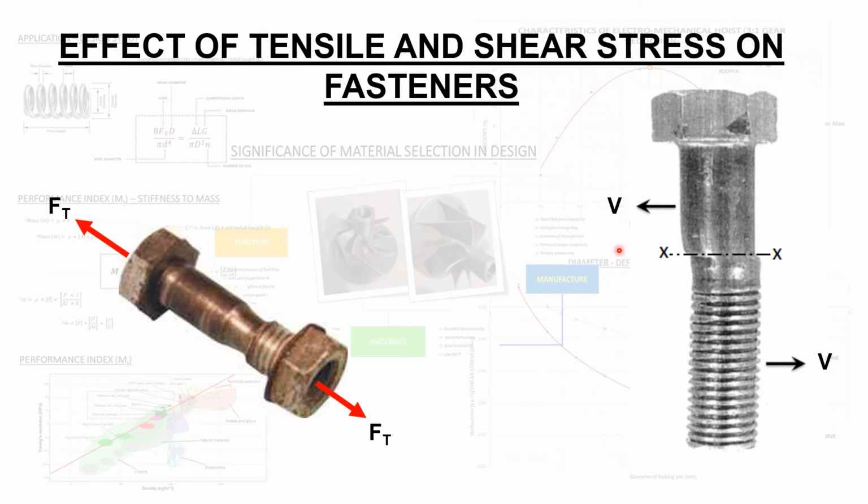If we look at this diagram here, you've got the plane of shear, and with respect to the plane of shear, we realize that the applied load has some considerable distance from the axis of shear. And the greater the load is, or the longer this load is applied over time, the component of the bolt will undergo significant distortion and eventually fail and shear along XX, or the axis of shear.